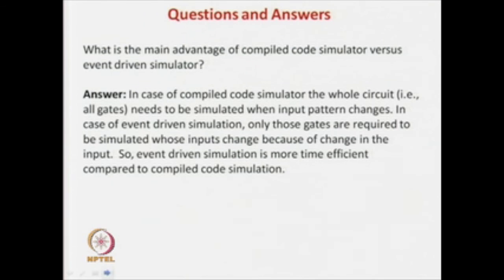So, the first question: what is the main advantage of compiled code simulation versus event driven simulation? We have already discussed this many times for concurrent fault simulation, deductive fault simulation, normal fault simulation and normal circuit simulation. In compiled code simulation, we convert the circuit into a program and execute it for a pattern. Then you forget everything. If you change anything, you have to redo everything.